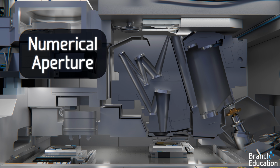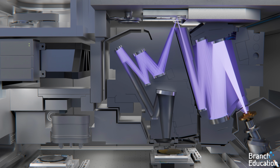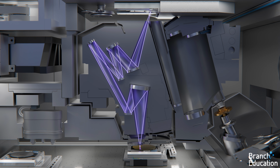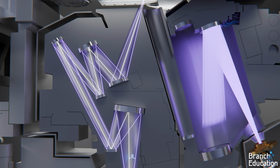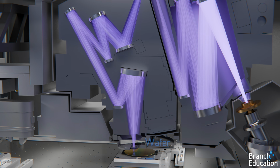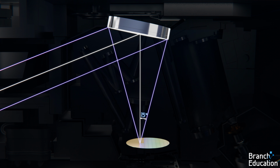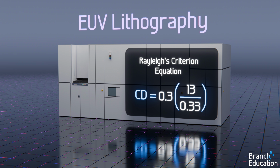Finally, numerical aperture, or NA, is a measure of the angle and amount of light the mirrors in the projection optics can capture and focus onto the wafer. Numerical aperture isn't just about increasing the brightness of the EUV light, but rather it's more of a measure of the angles and amount of constructive interference wave paths that hit the mask and then are projected onto the wafer. In short, with a larger numerical aperture, or NA, which corresponds to a larger angle between the projection mirrors and focal point, we can achieve a smaller resolution. This tool has a numerical aperture of 0.33.